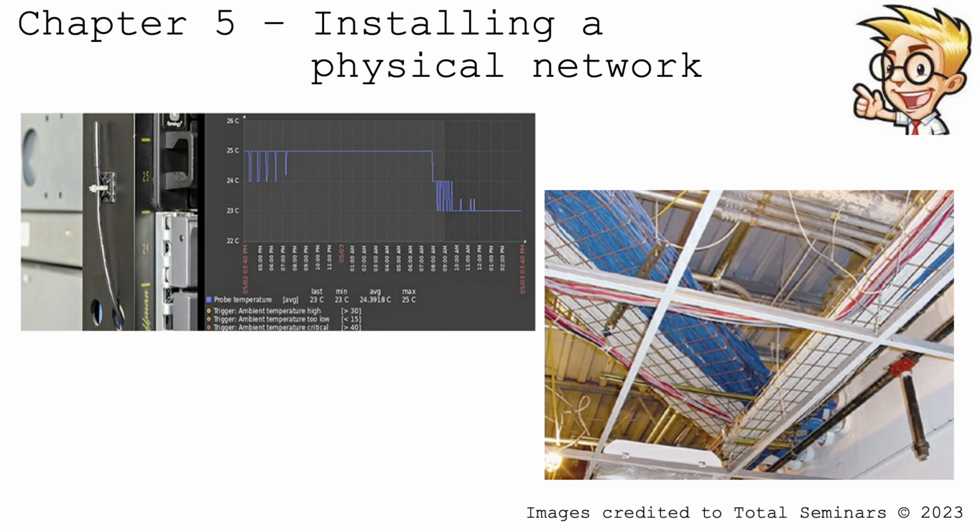Okay, here's another example of a cable run, but it's using a tray. So instead of drilling holes in the wall and crawling around, you can just run a tray over your head and over some equipment, and that way you can carefully see what kind of cables are being run this way and this way. So a bit more work, but in an industrial setting, that would be ideal.